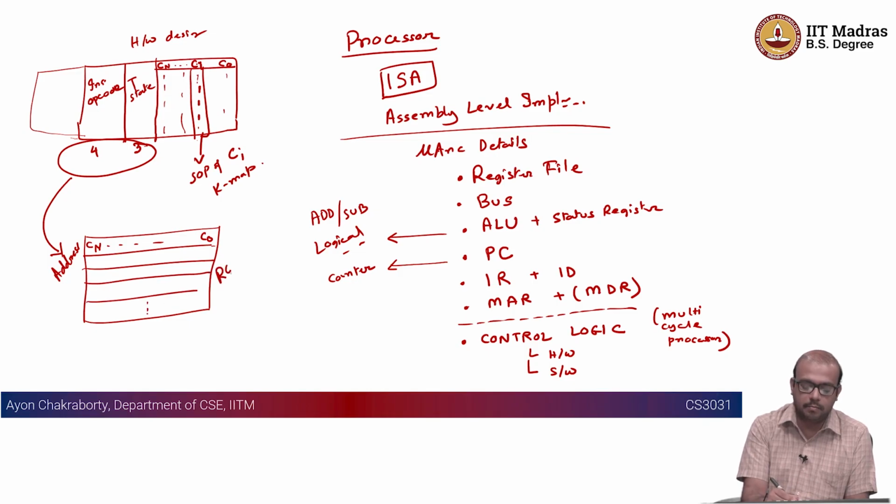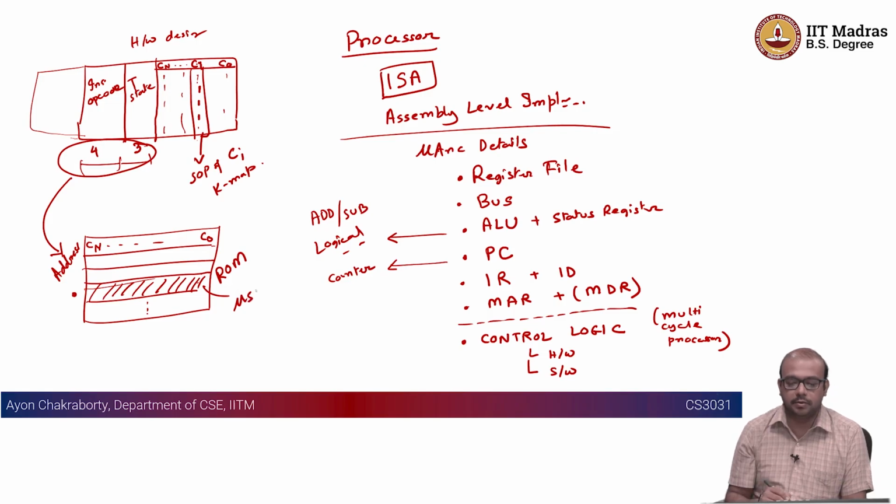So this is your ROM, and if I say give me the 57th line, it is going to come from this combination of a certain opcode and a certain T state. You are going to go to the 57th line and pop out the corresponding micro instruction, or the control word.